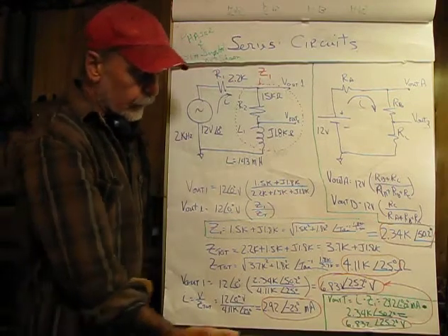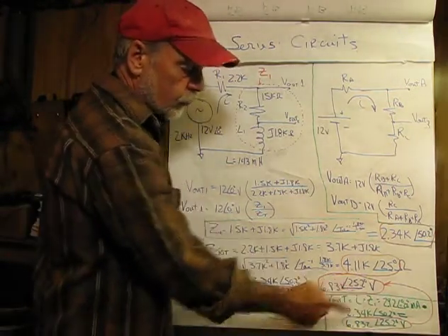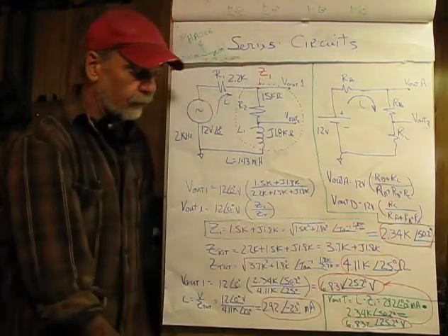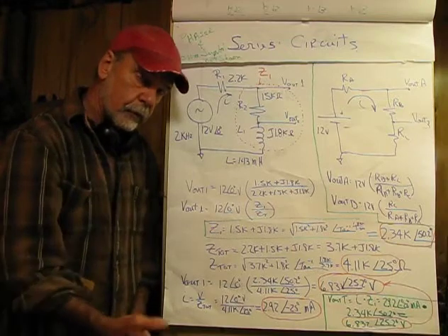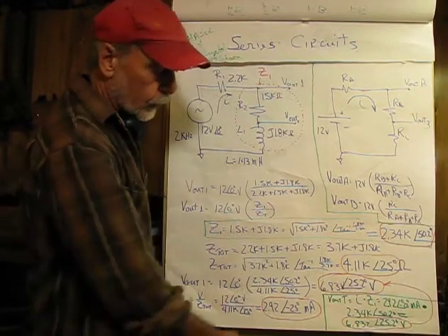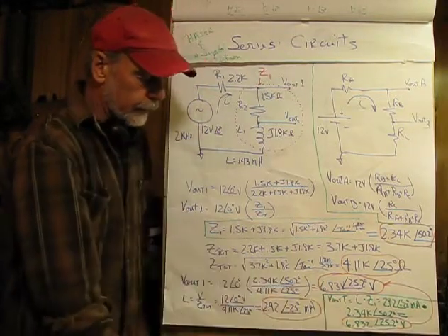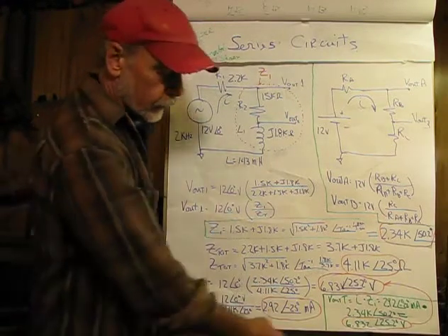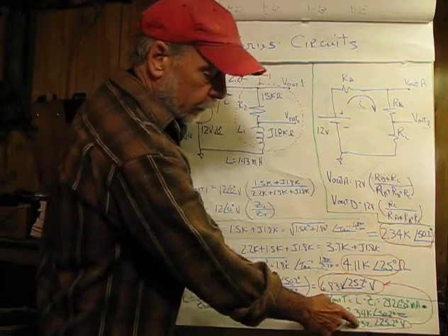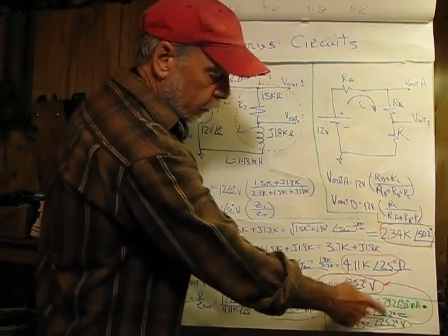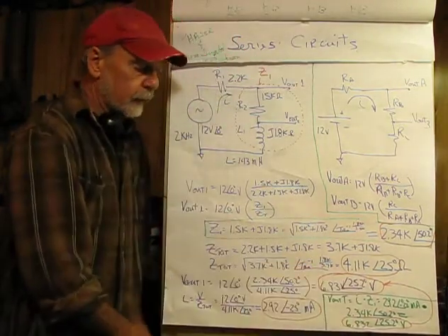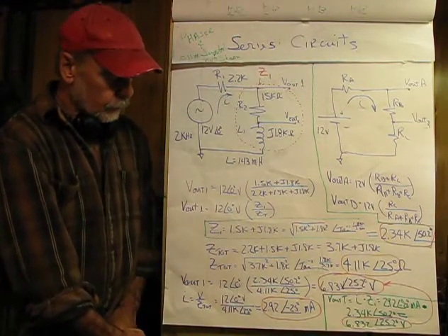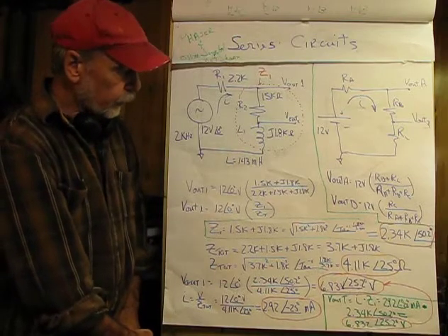So I'm saying V out now equals I times Z1, which is the 2.92 at negative 25 degrees milliampere current flow, times the value of Z1, which is 2.34K at 50.2 degrees. And fortunately I get 6.832 volts at 25 degrees, which corresponds exactly to the number we got from the voltage divider. So I'm pretty satisfied with that.